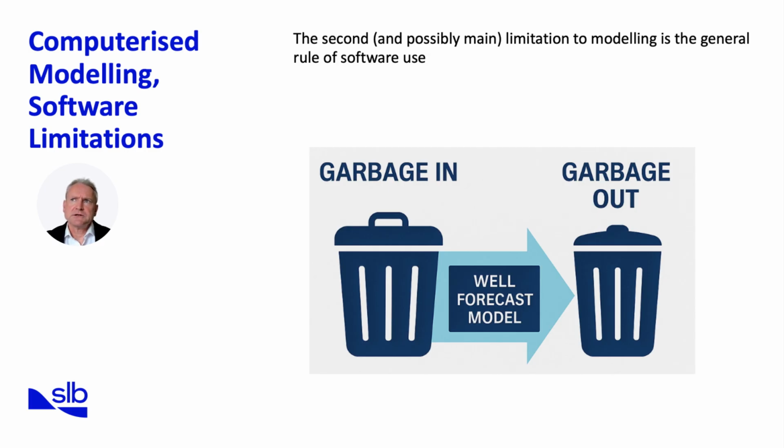Furthermore, software packages often rely on default parameters or simplified assumptions. For example, fluid models may assume constant rheology, or torque and drag calculations may fix friction factors. These assumptions can mask real variability in the wellbore. Another limitation is user overconfidence. Engineers may assume the software output is definitive, when in reality it is just one possible representation.